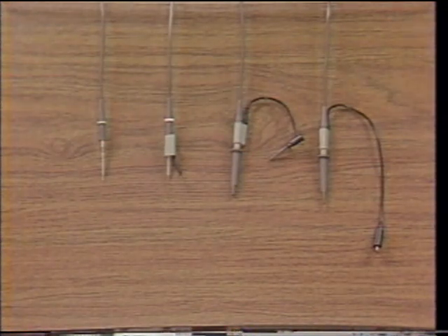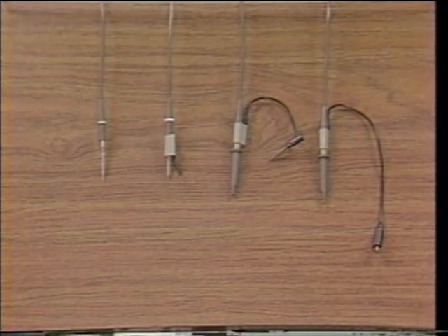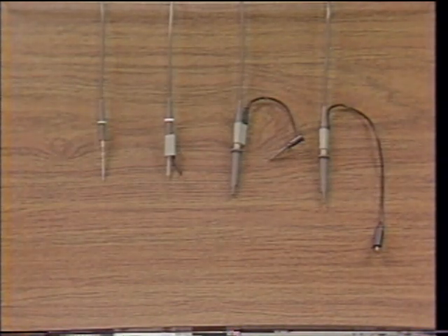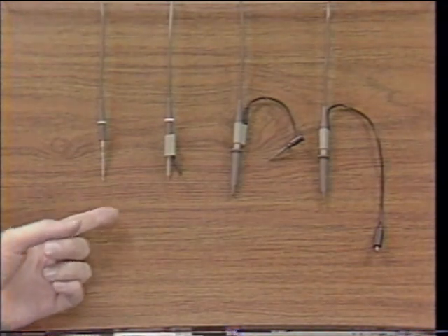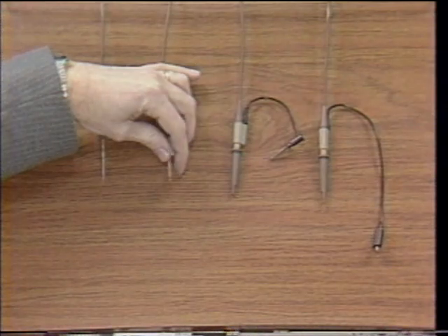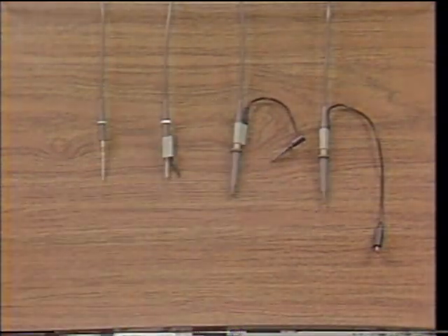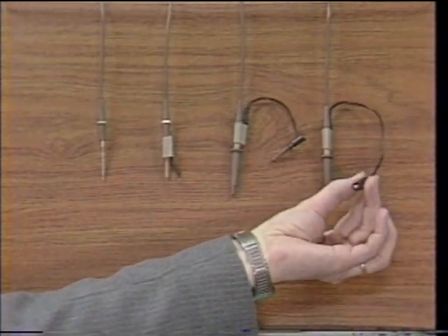The P6131 standard accessory probe for the 2465 and 2445 presents a 10 megohm and 11 picofarad load to the signal under test. It's available, or it can be configured, in 4 different grounding configurations, as we see here. We have a coaxial configuration, which is simply a bare metal ground exterior and a signal input at the tip. We have a Z ground, which can be pivoted to adjust the spacing between a ground point and the signal point. A hook tip, which can attach to an axial lead device or a DIP pin. And finally, a rather long alligator clip ground.